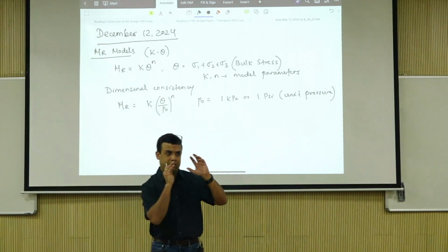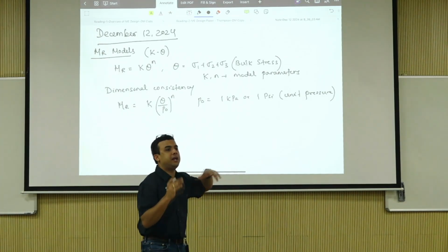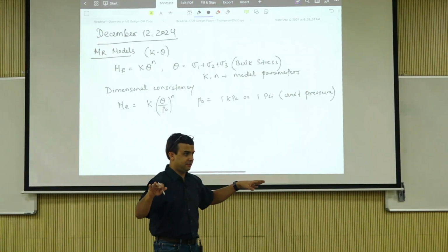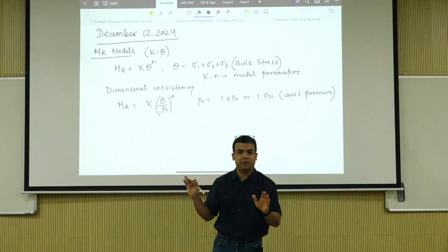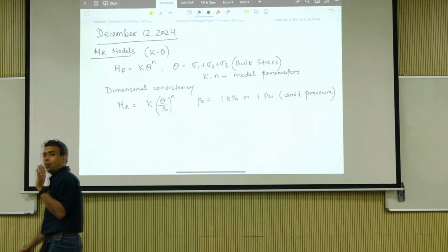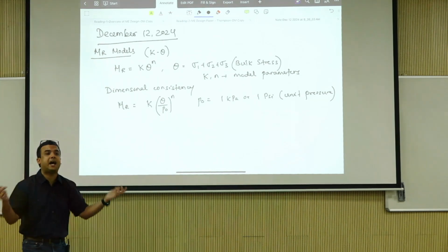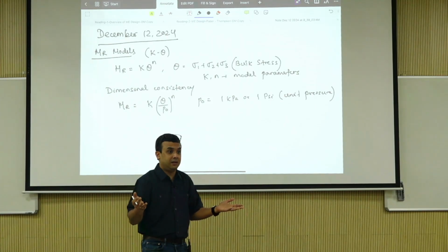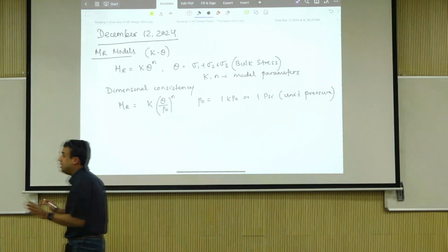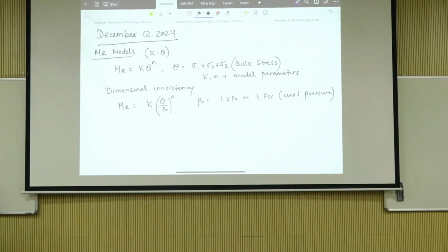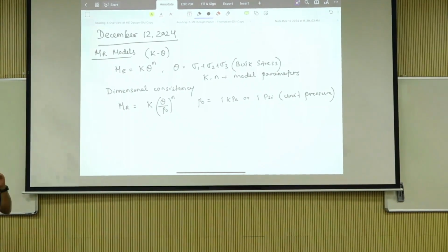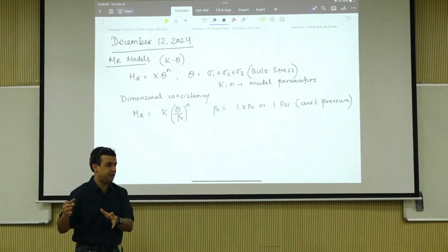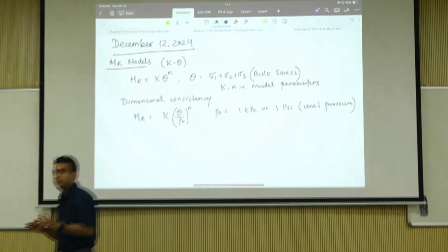So where do K, n, K1, K2, K3 come into the test file? Nowhere, right? So that's something you have to be very clear about. It is quite possible that you can spend your entire life only running tests and not fitting a single model, if that's what your objective is, right? So your test data will not give you any of these parameters. The parameters are needed because you are going to do some calculation for which you want to represent MR as a function of stress state. That's basically the whole purpose, right?